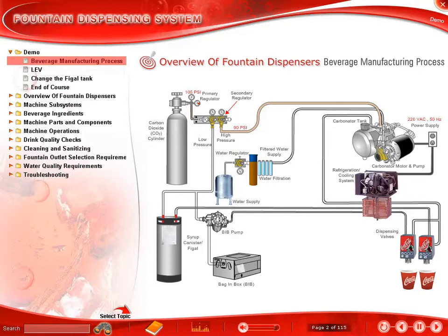Water makes up over 80% of the beverage, so both the quality and quantity of water is important. The typical post-mix dispenser requires water volume of 100 gallons per hour to meet typical operating demands and maximize the efficiency of the dispenser. 40 to 75 psi of water pressure. A water source line at least ½ inch in diameter with a separate shutoff for the carbonator. Water regulator regulates the incoming water pressure to 55 psi, preventing flooding of the carbonator tank in locations with high water pressure.